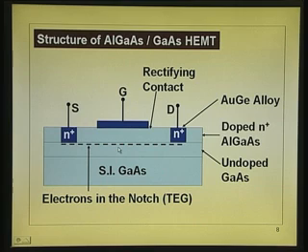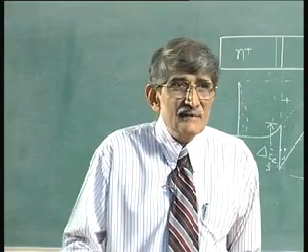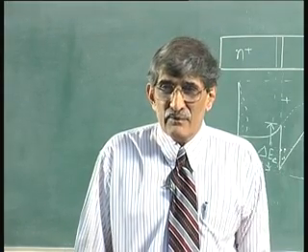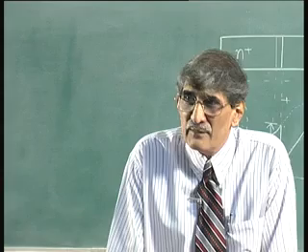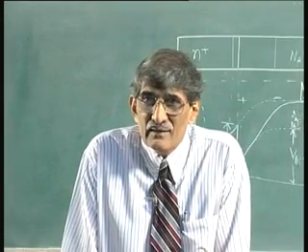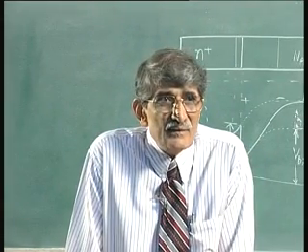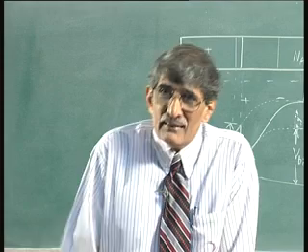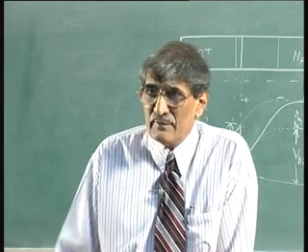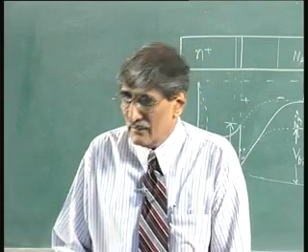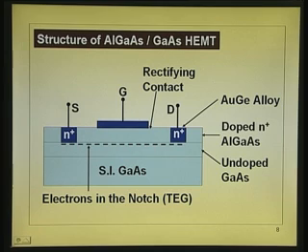Okay. Just like in the case of MOSFET. In the case of MOSFET, once it is inverted, you apply voltage between the gate and the source, the charge in the inversion layer gets affected. For example, above the threshold voltage, if you apply VGS, that VGS minus V threshold appears across the oxide, and that changes the charge. Similar thing will happen here. I am not discussing it right now, because I am just giving you the principle. We will go into more of analysis after discussing few aspects.